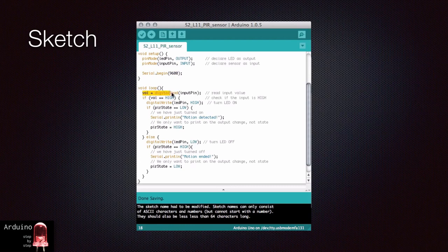In the loop function, we constantly read the value of the PIR sensor by using the digitalRead(inputPin) function. This function reads voltage in the range of 0 volts to 3.3 volts, at least for the sensor I'm using, and the Arduino translates that to LOW and HIGH respectively. If HIGH is detected, the Arduino will set pin 13 to HIGH, and this will activate the LED.